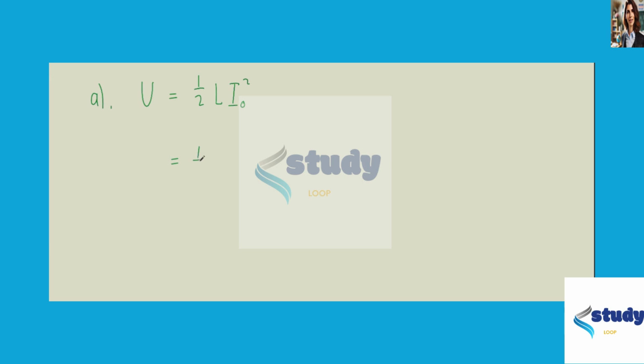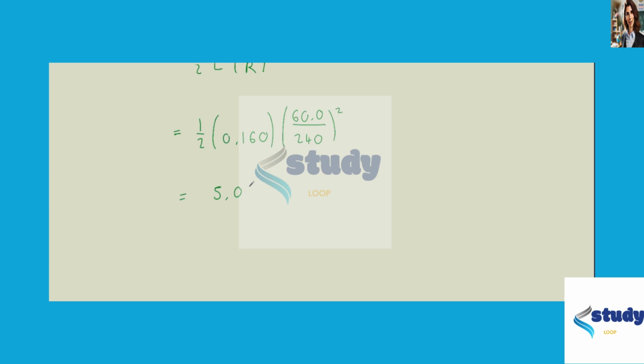And this can be written as a half times L times the EMF over R, all squared. And these values are all known. So this is a half times the inductance of 0.16 henries multiplied by the EMF, which is 60 volts, divided by the total resistance of 240 ohms, and that's squared. And hence we get the energy stored in the inductor initially to be 5 times 10 to the minus 3 joules.